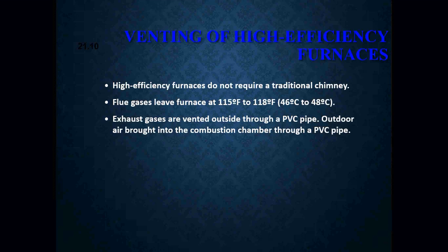High efficiency furnaces do not require a traditional chimney. Your flue gases leaving a high efficiency furnace can be anywhere between 115 and 118 degrees. Exhaust gases are vented outside through PVC pipe. Your outdoor air brought in for combustion is also through a PVC pipe.